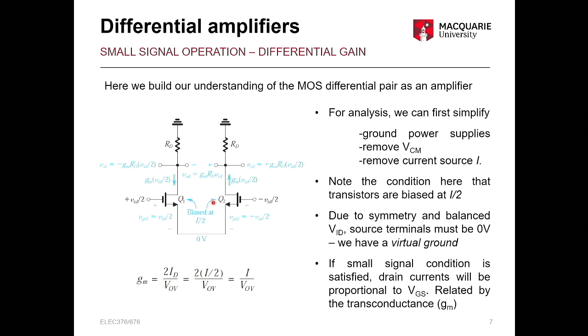And we discussed last week as well the virtual ground condition. So that's, you get 0 volts at the source, and I showed a kind of quick derivation for that to prove it. Remember, that's only valid if you have your differential input applied in a complementary way. Okay, so plus half on one side, minus half on the other. That's the condition you need to get this virtual ground state, which means this common source is stuck at 0. It can't really move beyond there as long as the rest of the circuit stays in its typical conditions.